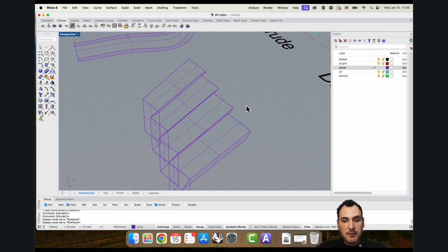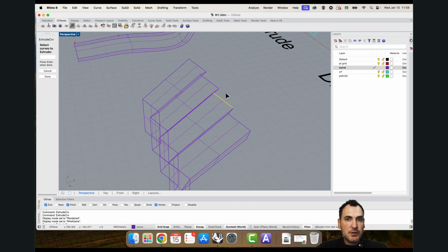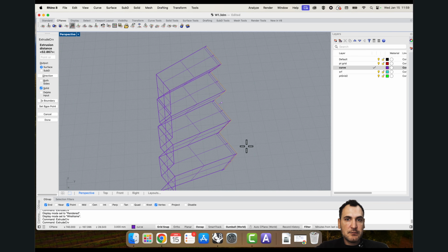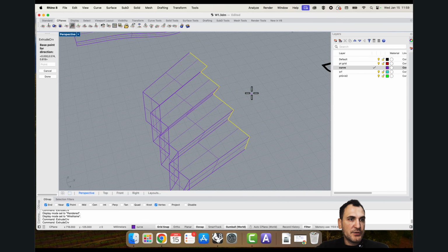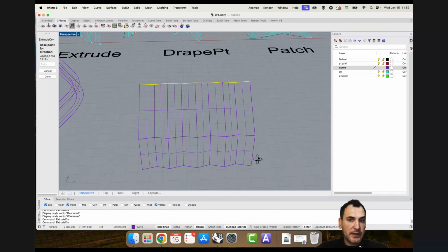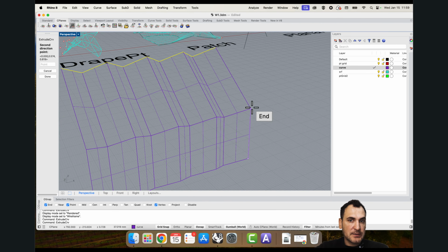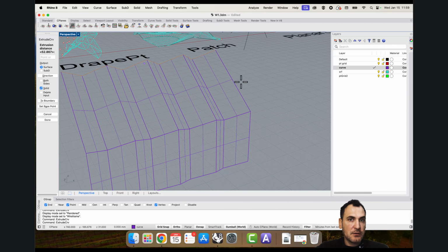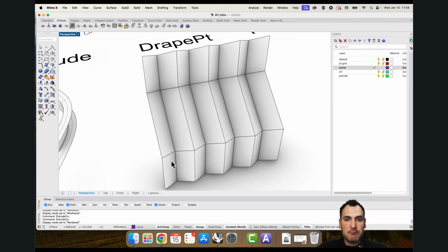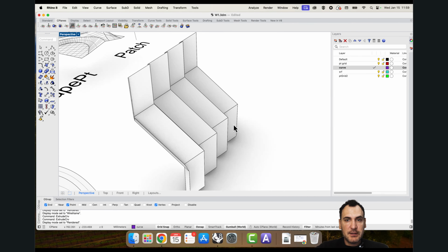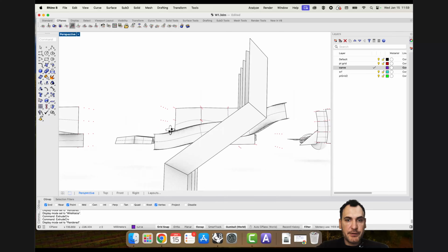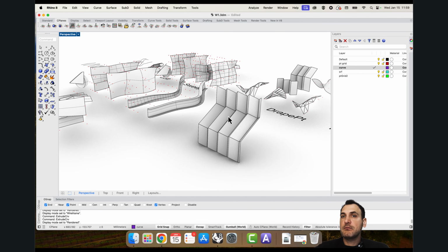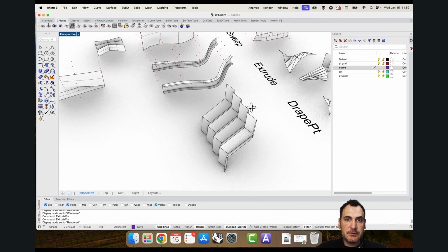And we can essentially keep going with this, right? So I can do extrude curve, choose all of these boundaries for direction. I can also manually input directions, but I can also grab it from somewhere else. Let's say I want to grab this edge here, and I want to go up. Okay, so that's essentially like this fold is happening along this corner, but we were able to control how to fold or extrude the rest of the surfaces.